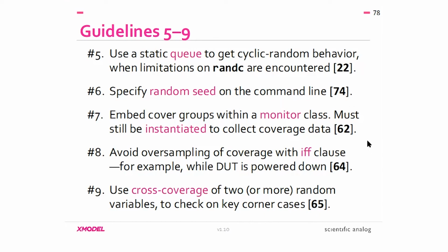Guideline 7, coverage. In a UVM compliant test bench, all of the cover groups and cover points would likely go within a dedicated class called coverage. We found it easier to put the cover group inside the monitor class. However, keep in mind, it still has to be constructed before you can gather coverage data.